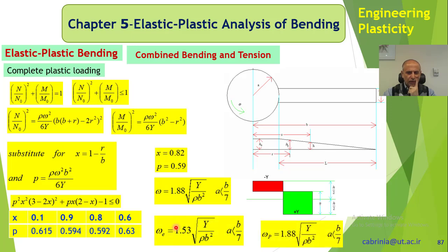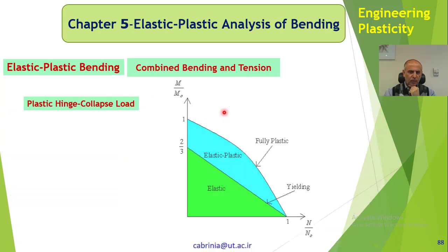And also we have these relationships for the elastic angular velocity and completely plastic angular velocity. Okay, so you can see we can analyze almost any kind of problem, even very difficult ones, but we used our analysis of bending and plastic moment to solve this kind of problem.